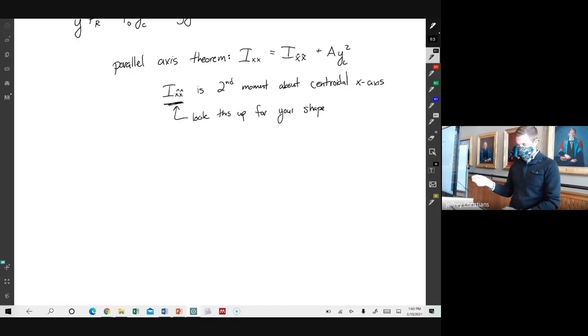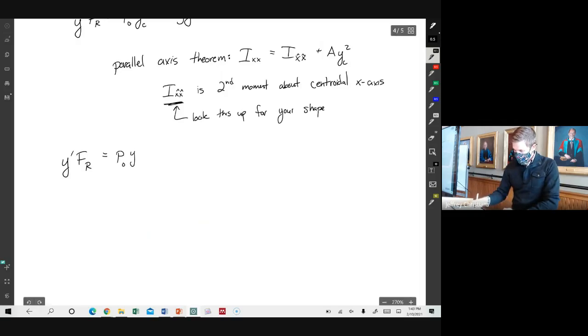Okay, so now again, let's plug that in, because the hat version is the one that we can look up. It's going to get a little bit ugly, and then it will simplify somewhat. P naught yc A plus rho g sine theta, and then we plug that in with the little hats, plus A yc squared.